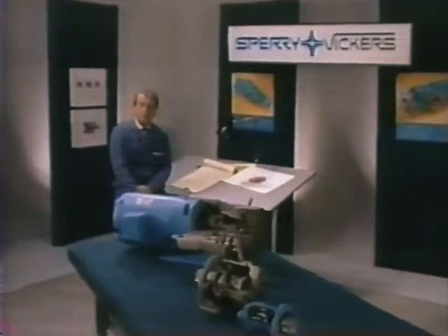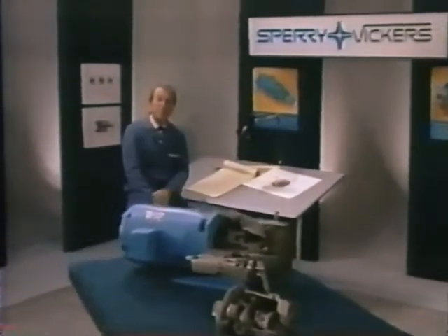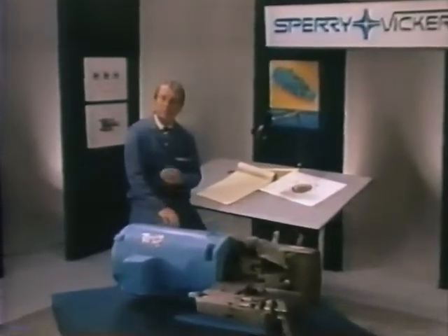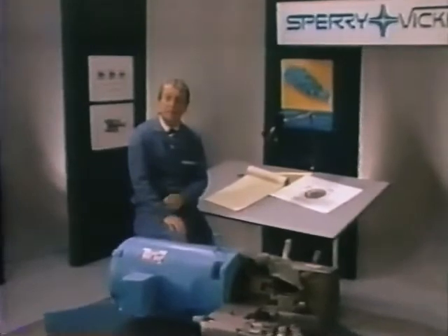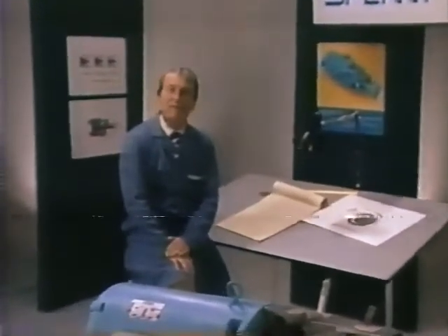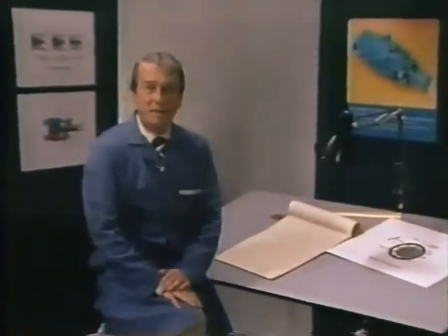Pumps and motors used in hydrostatic transmissions can be vane, piston, or gear type. Piston units are probably the most common because of their high efficiency and their pressure capabilities, and the fact that they're available in fixed and variable displacement models. Now, let's take a closer look.